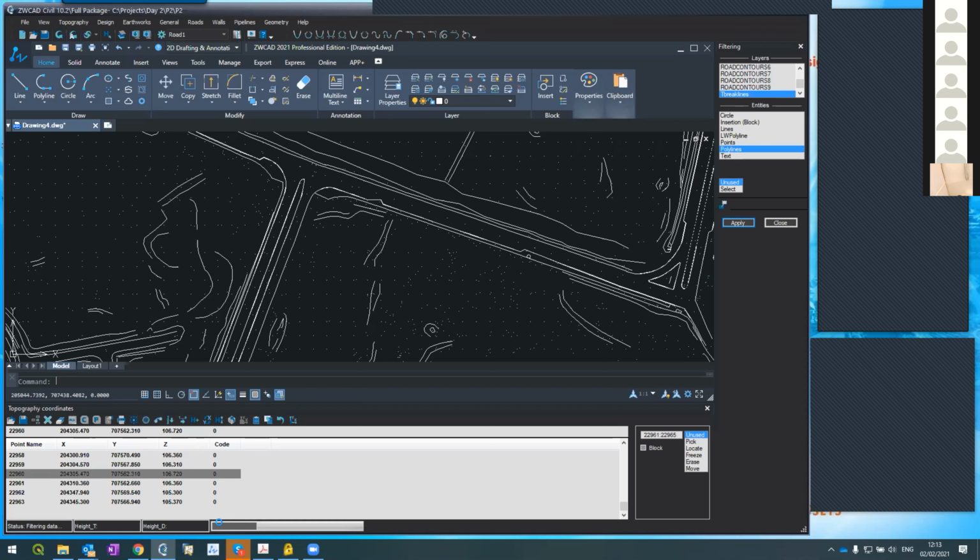Of course, I can create contours without break lines, like we did in the beginning of this lesson, sample 7. But in this case, if we do not use break lines, the contours will not be fitting. The surface will be wrongly made. Yeah, we are halfway there. It still says filtering in the status.